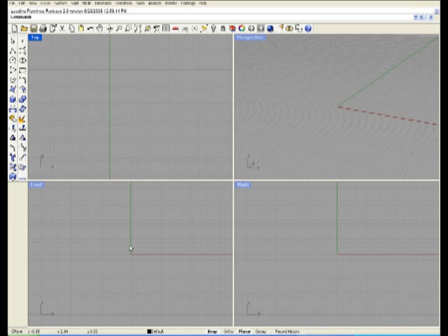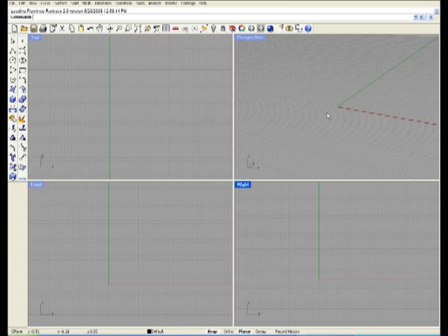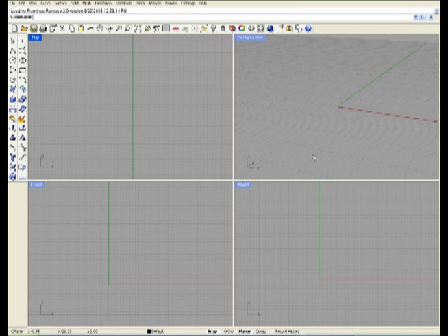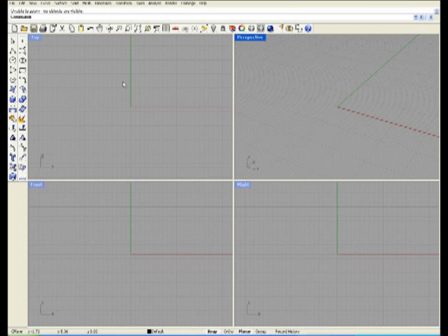Okay, now we can do it on the front view, on the right view, and on perspective. When we use the right click on perspective, what we're going to do is rotate. We're going to rotate in any of the axes that we need: Z axis, Y, and X. Okay, so if we need to go back to our normal view, like all the 4 views together, then we have to double click on this icon that says 4 viewports and right click twice. If you right click twice, you're going to get all your views as they were in the first place.